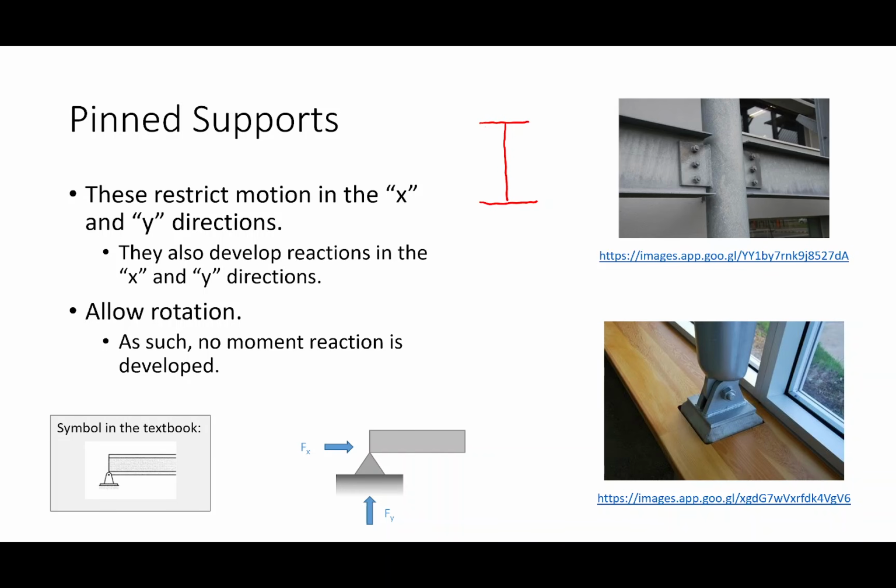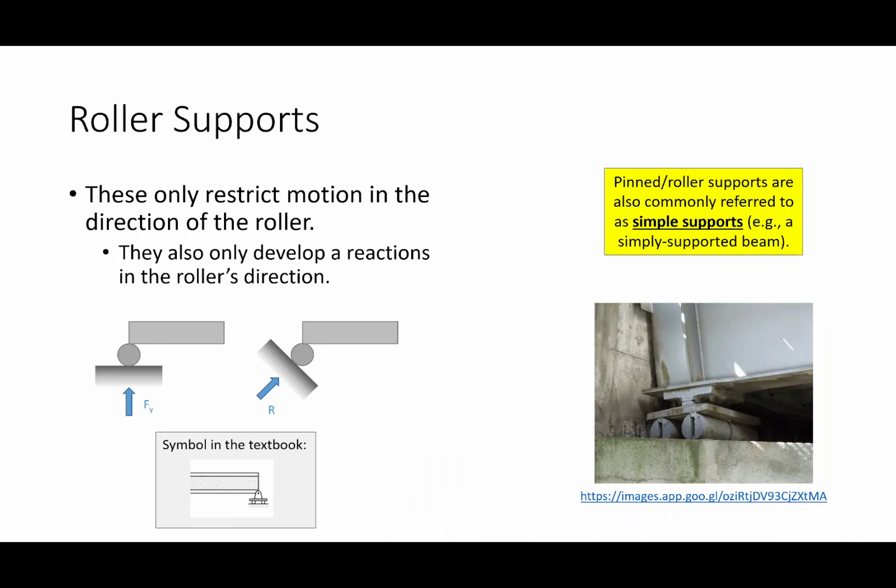All right, good. Okay. Now here's a pin support. Let's talk about a roller support, okay? Now roller supports only contain one reaction, and that reaction is in the direction of the roller, okay? Now I will draw that as a circle, right? Sometimes in the textbook you'll see this little, tiny skateboard looking thing. But essentially roller connections allow translation along the axis. Commonly, they allow translation along the axis of the member. Sometimes we'll have inclined rollers, which we'll talk about actually sometime next week.